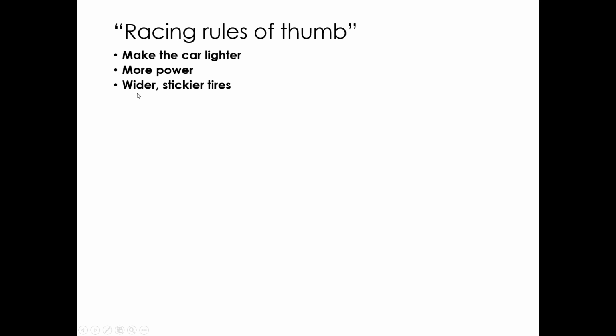I haven't talked about wider tires at all. If you just look at the coefficient of friction model, there's no area in there, and why would making a tire wider give it more friction? It does. You can see that from any tire model. You can see that in drag racing. It doesn't actually change the area of the contact patch on the ground that much. That's more a function of the tire air pressure than the tire width.